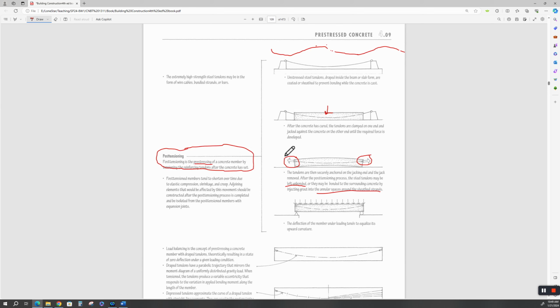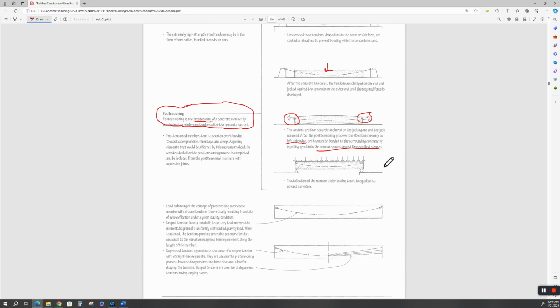I am not a big fan of post-tension slabs, especially for residences down here, because it all depends on how good that construction crew is. Now, commercial post-tensioning, where you have a set of specs and an inspector that's supposed to be paid to watch what the contractor's doing, and testing labs and that sort of thing to watch the pressure gauge and monitor what's happening to the concrete deflection-wise is one thing, but we know that does not happen in residential construction. You got a lot of chucks in a truck doing this.